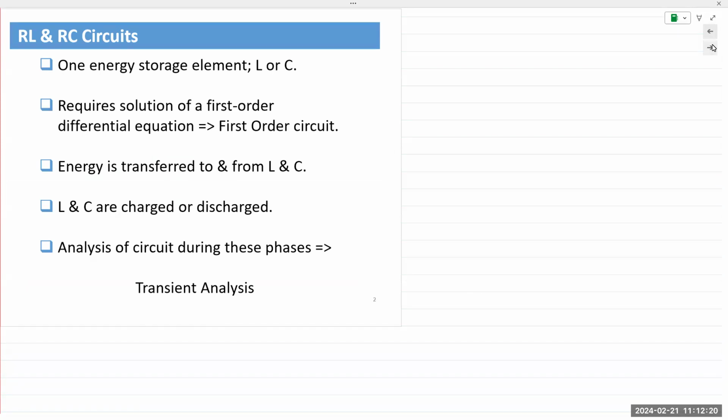We look at different circuits, each containing an inductor or a capacitor. But when we say it is one component, we are referring to the total equivalent value of multiple components in the same circuit. So you could have multiple resistors in the same circuit, and we reduce it down to one single resistor. We call it Req. Similarly, we can do so for inductor and capacitor, Leq and Ceq. Okay. So that one refers to the total equivalent value of that inductor or capacitor. So we could have Req, Leq, and Ceq.